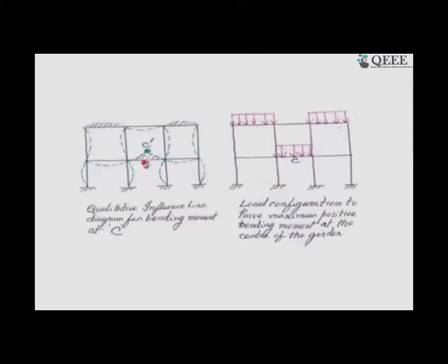It is immediately apparent, if you explore which part of the building frame should be loaded to have the maximum sagging bending moment here. Here is the answer: you have this point which is the positive part, this point positive, this point positive. So, you load it here, here and here, and you get the maximum. Also it says, since this is negative, you should not load it vertically downward. You may load it vertically upward if possible, but that is not discussed in a building frame.